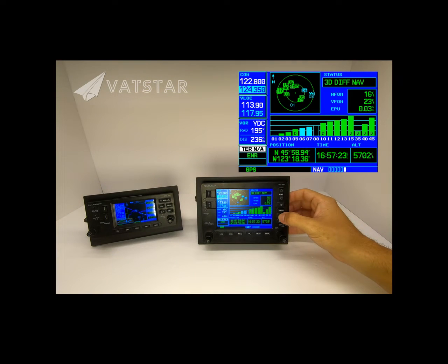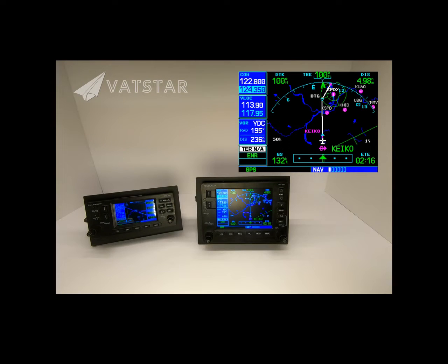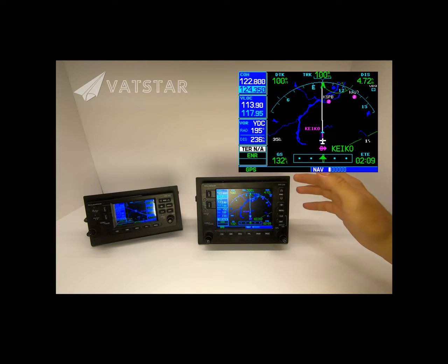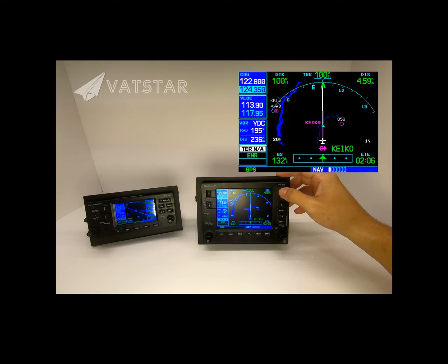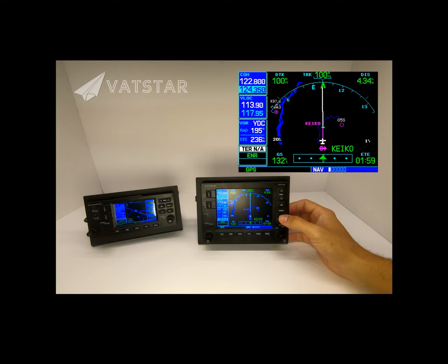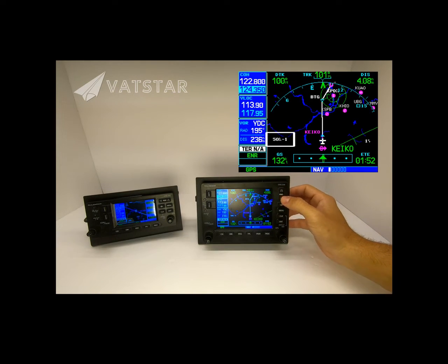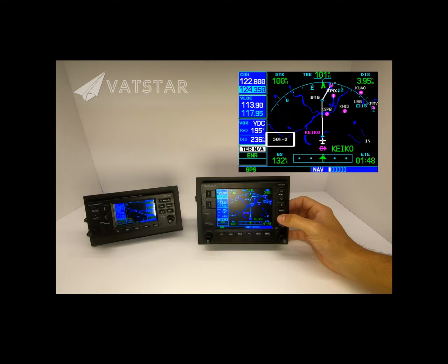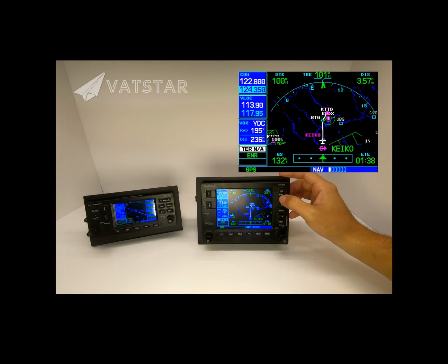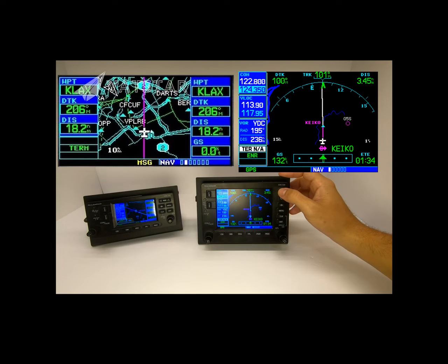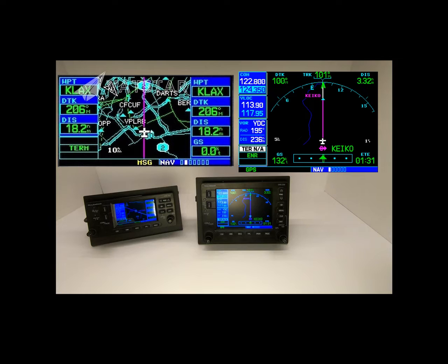So I'm going to press and hold the clear button, and it's going to bring me back to my default screen. And then if I zoom in, you can see how far and the details of the map. And talking about details, how much information do you want to see on your screen? You can switch it very easily, by pressing the clear button different times. So if you press it once, let me zoom out, you're going to see how the more you press, the more information goes away, and it's just down to the basic ones until you get them all back. Whenever you're flying in popular, very active areas like Miami or whatnot, you're going to have a lot of information, including roads and things like that.